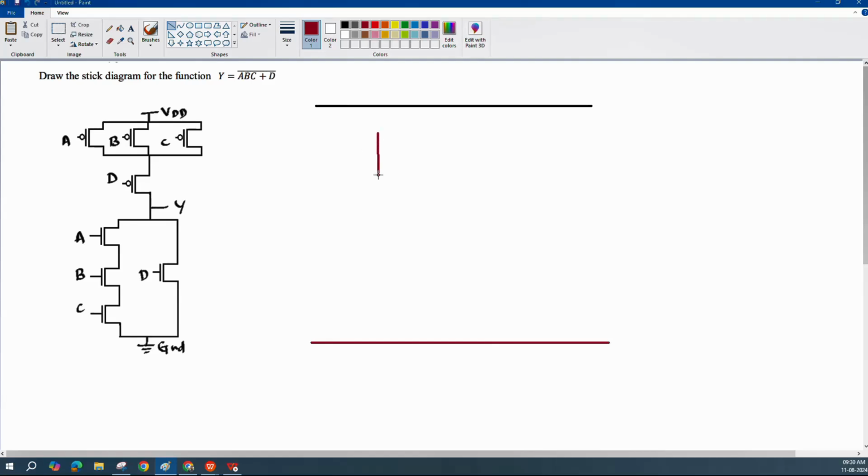for the gate of the transistor, and we can place 4 transistors over here, and horizontally I am taking source and drain of the transistors. These are the P transistors representing the diffusion with blue color here, and in your exam you can write without any color representation, that is not required. So now here we have 4 PMOS transistors and I have taken 4 NMOS transistors. NMOS transistor diffusion, that means source and drains, are represented with green, and the red indication is for gates, and blue indication for the PMOS diffusion.